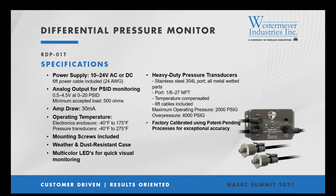Operating temperature for the electronic enclosure is -40 to 175 degrees Fahrenheit. The pressure transducers can operate between -40 and +275 degrees Fahrenheit. And they come with a 6-foot cable and a 1/8" male NPT thread. The maximum operating pressure is 2000 psig, and the overpressure protection rating is 4000 psig.